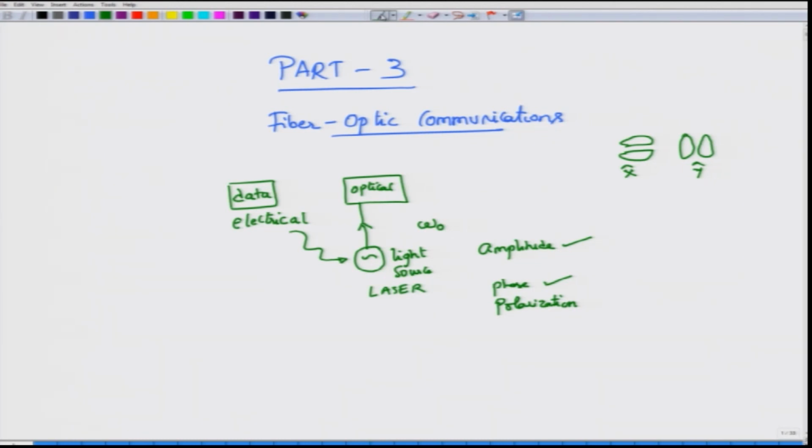So, to sum up, you need to have data in the electrical format and then convert the data in the electrical format into the optical format, or into the optical domain. Now, how do we go about doing that? We know that a laser source is essentially a forward biased semiconductor junction, right. So, it is a PN junction which will be producing light when we send in some amount of current, which would be the forward current of a forward biased PN junction acting like a laser.